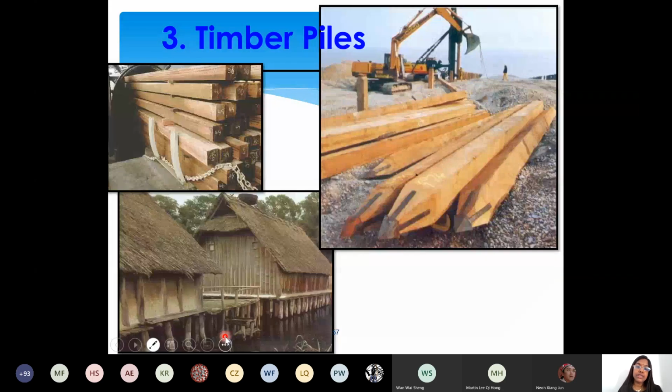Okay, I see the pictures, see how it is. These are the square piles, and the pile tip is like this. This is anchored to the ground. And see the construction in Malaysia, I think Sarawak, most of the coastal regions and tropical regions. They will use this type where there is watery and swampy area, right? Loose soil, more loose soil. You can go for this type of foundation.